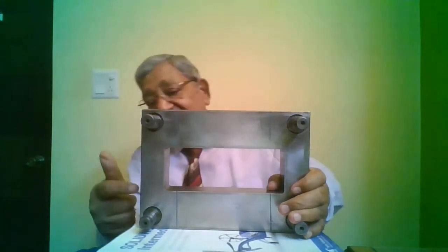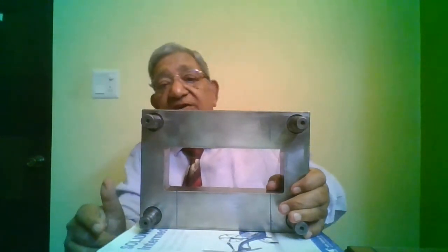They are drilled holes. So by creating a pocket and these two cooling holes, the cavity plate of the mold base is converted into the cavity plate of the mold.